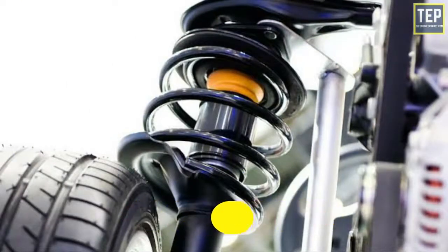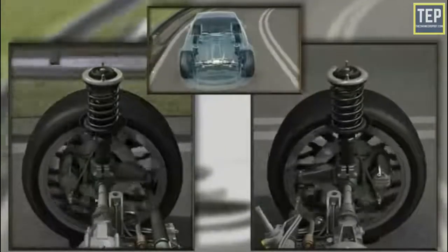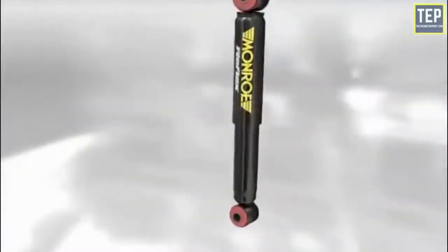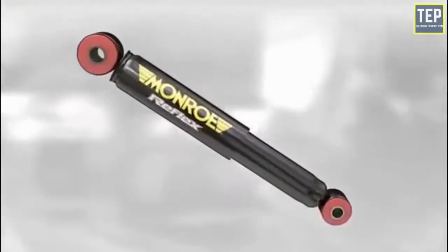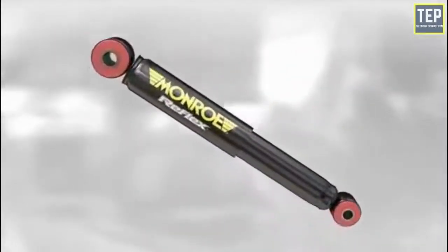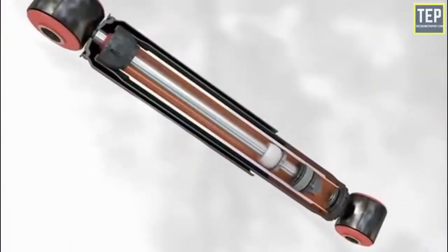Dampers, commonly known as shock absorbers, protect the chassis from the force caused when a wheel hits a bump and prevent the springs from continuously bouncing. They also push the wheel back to the road surface. A damper is a piston filled with oil that separates the chassis from the wheel. When the car hits a bump, the piston pushes into the casing and is slowed by the oil, which flows into another chamber as it's compressed.